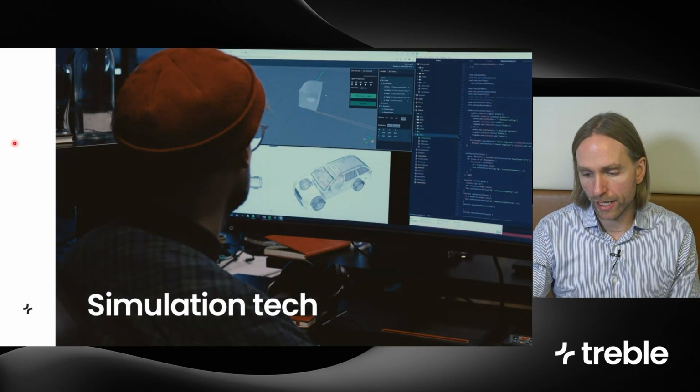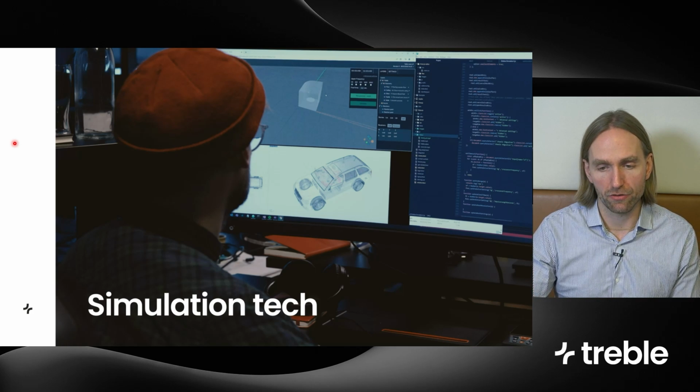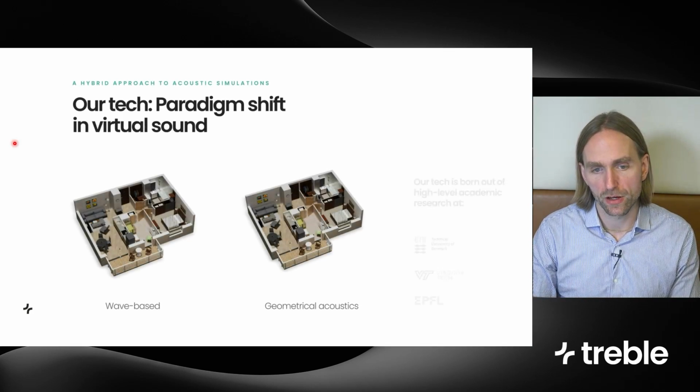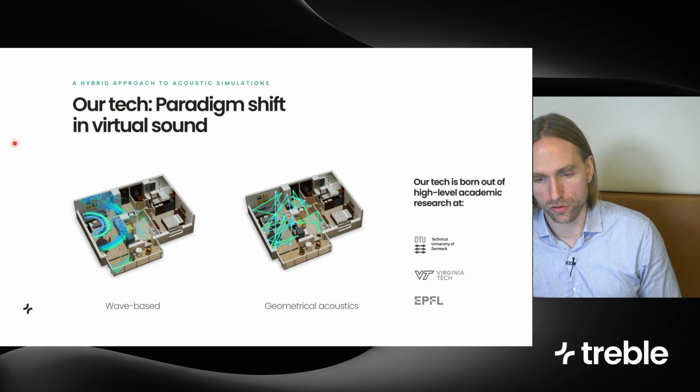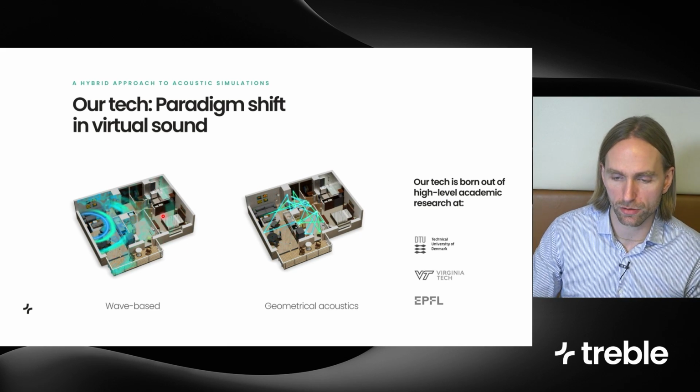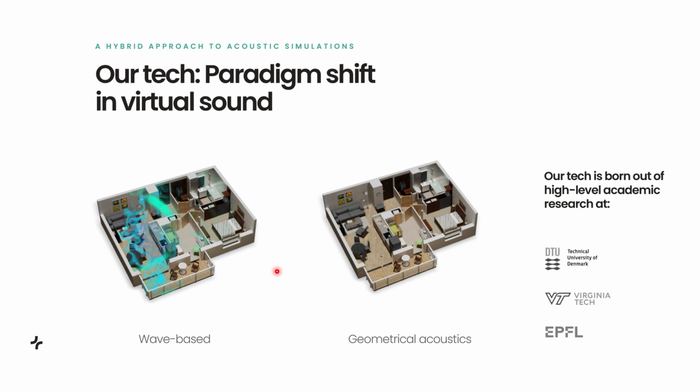Okay, but zooming in on the simulation technology itself, the core engine. So our approach to acoustic simulations is a hybrid approach. We combine two different methods of simulating sound into a single approach. This uses what's called wave-based methods for the low to mid frequencies and geometrical acoustics for high frequencies.